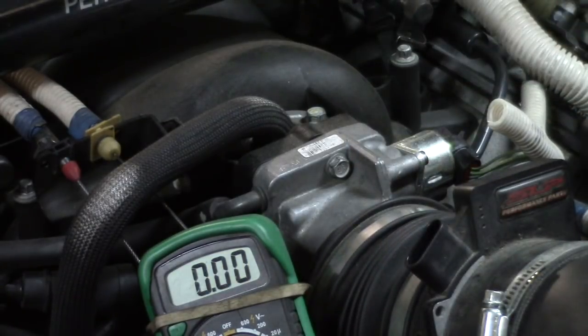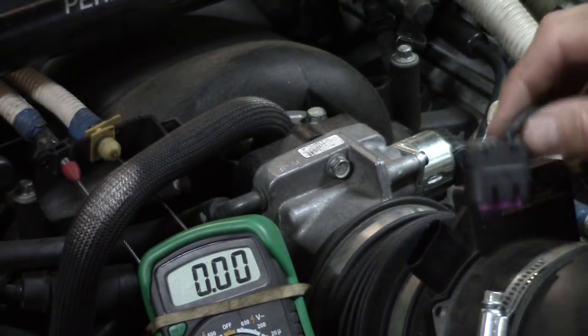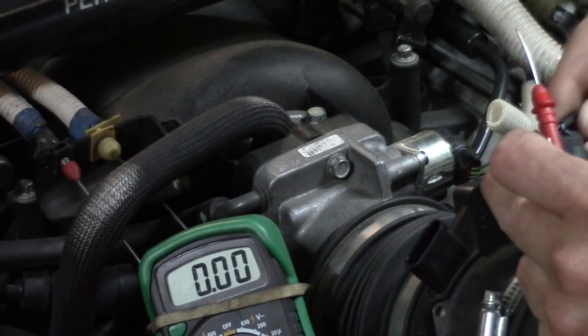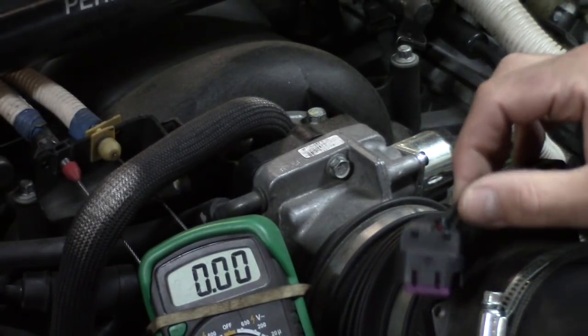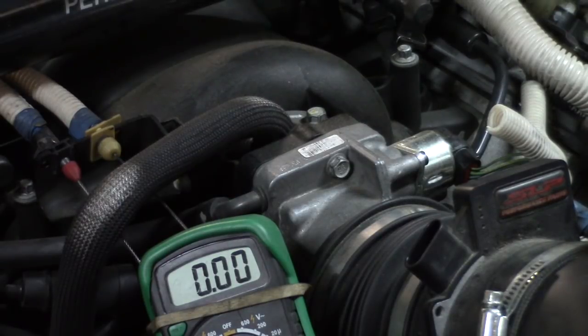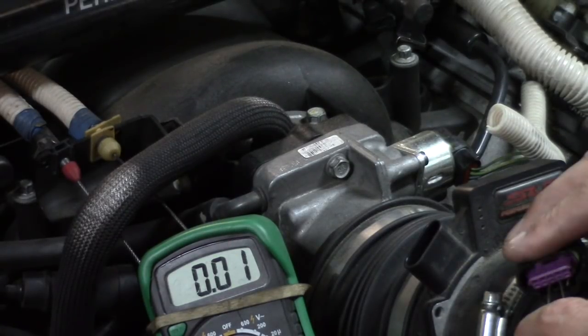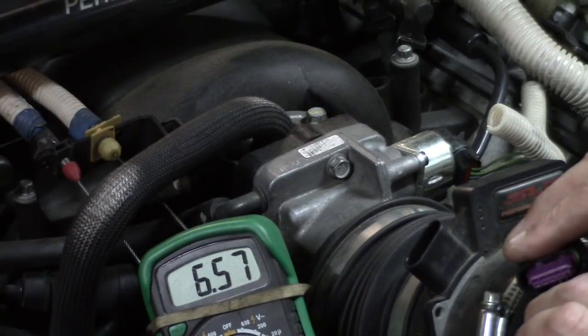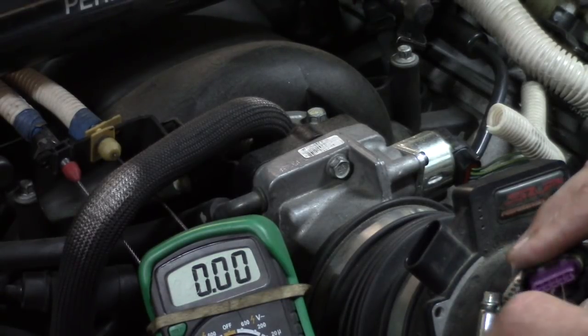So obviously, understanding our MAF application here, we've got a 3-wire sensor. We, of course, may not even know which wire is which, but we're going to look and verify that we've got a power, a ground, and a signal. Okay, so if I just go ahead and probe these two here, we see that I get almost 7 volts, so obviously that's what that other guy did. That's clearly my power and my signal.